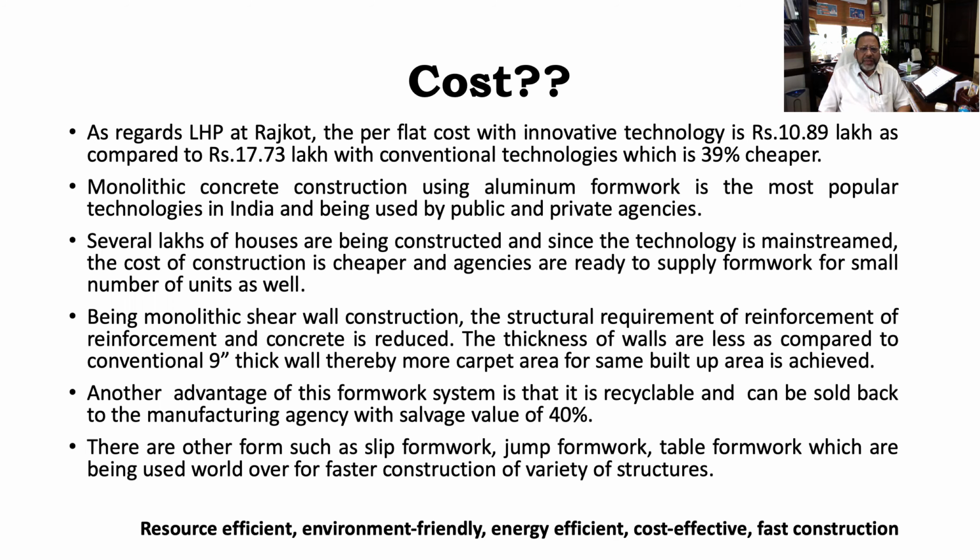Now, there is another important aspect of this tunnel form technology. Because it's a shear wall construction, the structural requirement of reinforcement and concrete is reduced. So instead of the conventional thickness of 9-inch wall, the thickness is reduced to 4.5 inch or 5 inch. Thereby, you have less requirement of reinforcement as well as concrete. And another important thing is that you get more carpet area for the same built-up area. So it is cheaper, number one. Secondly, for the same built-up area, you get more carpet area, so more movable space within the dwelling unit using this kind of technology.